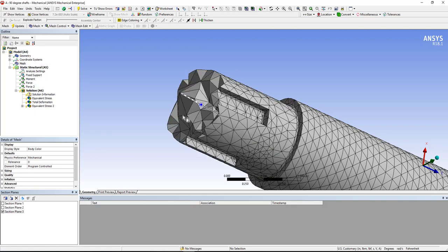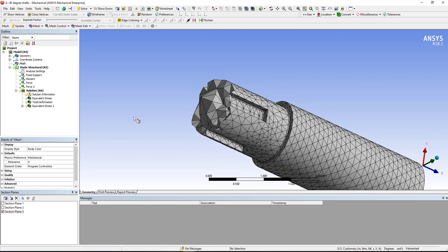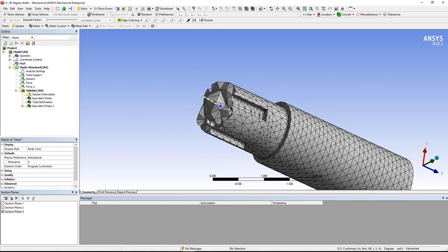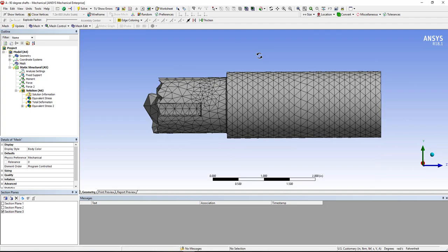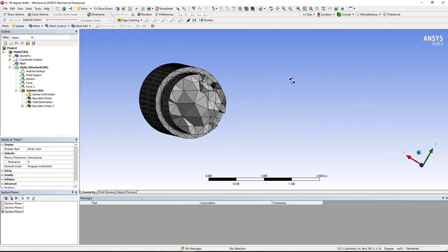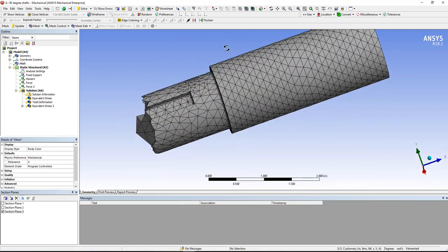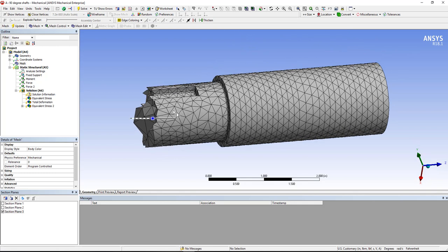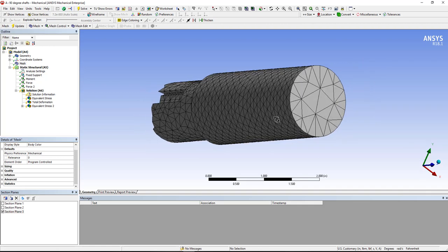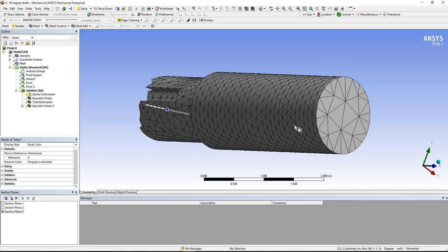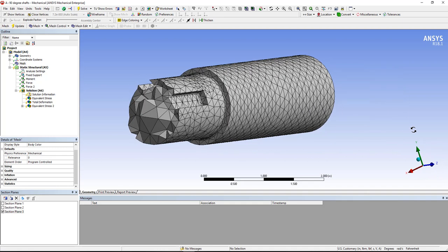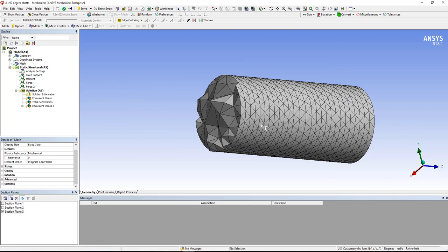Okay, so I can see that I need a better mesh. Now you can also see that these are tetrahedral elements, little pyramids, which are easier to create an automated mesh for, but they don't yield as much accuracy as quickly, and so you need finer elements. So now back in this area, even there, that's probably a little coarser than I may want for some of those. Let's drag this along and see.